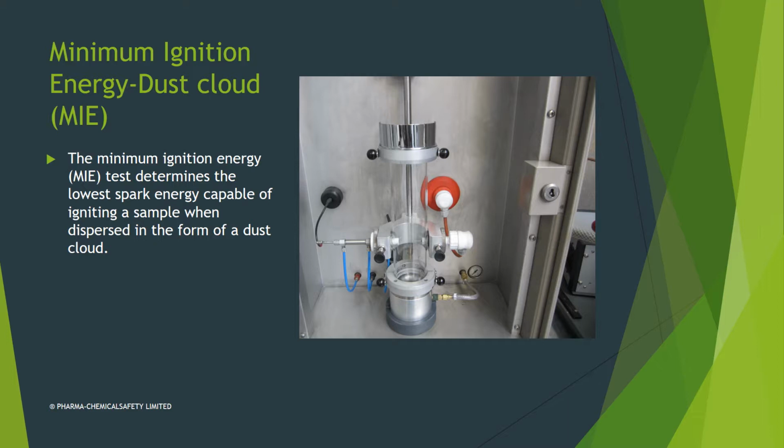You see the ST3s, you see the classification, the ST3s as well, they have the lowest minimum ignition energy. When you have, for example, less than 10 or less than 3, that means the dust that you are generating from that process, from the powder you have as a raw material, is very explosive. It's very combustible. It's not explosive like dynamite. No, this is very combustible because it doesn't need too much energy in contact with air to generate a deflagration. That's the right term to use.